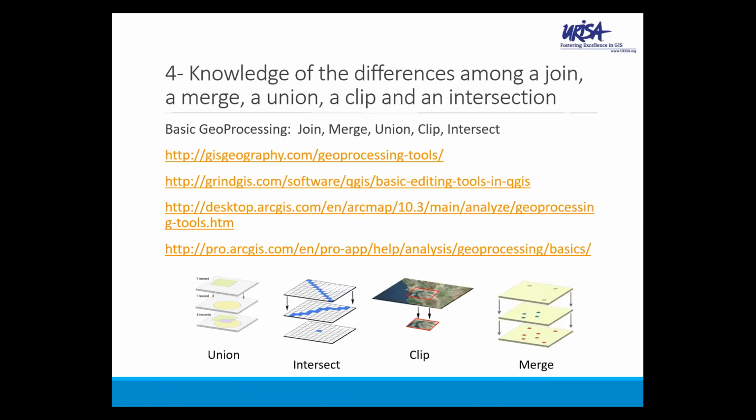Mechanically, it's done differently in every GIS system, but there are some common threads that we all see, and that they generally involve some kind of an indexed field that has to occur both in the spatial data and in the tabular data. So we look at that as a tabular join, or we of course can do a spatial join where we join tabular data to spatial data simply on the basis of geography.